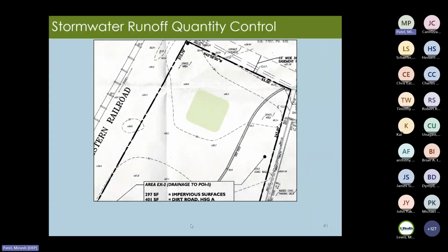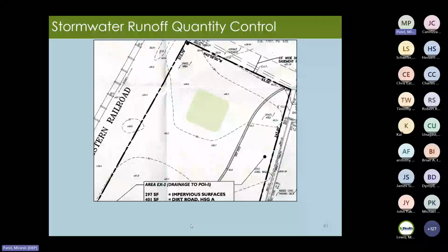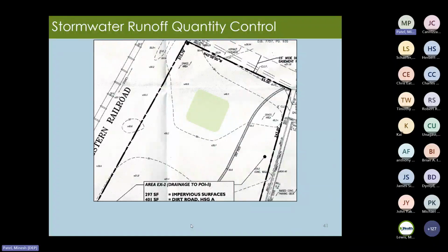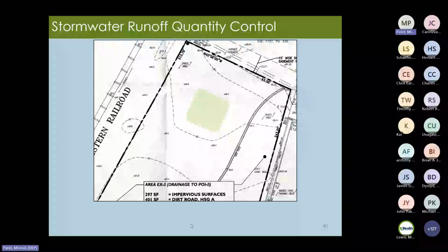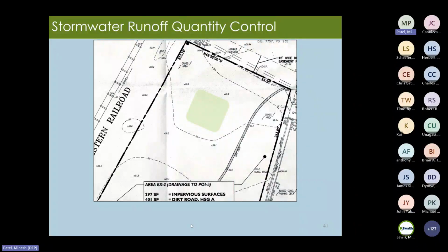So on the same example site that was shown before, there was a 6-inch deep ponded area within the shape depicted. This was ignored, and the basin was made significantly larger than was actually needed. If there are any questions as to whether areas of ponding exist on site and it cannot be determined from the photos of the site, you may actually have to go there in person and see.